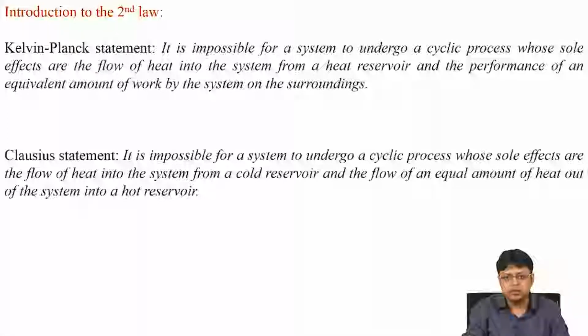The first one is known as the Kelvin-Planck statement. It is based on Carnot's work, and it was a revised statement given by Lord Kelvin, also known as William Thomson, and Max Planck. The statement says it is impossible for a system to undergo a cyclic process whose sole effects are the flow of heat into the system from a heat reservoir and the performance of an equivalent amount of work by the system on the surroundings.